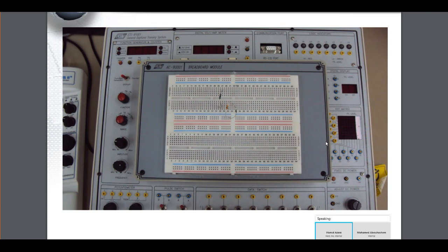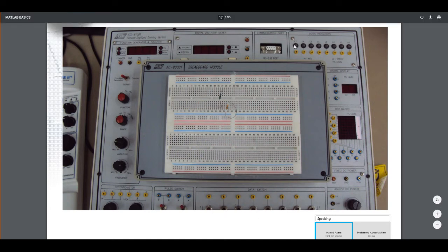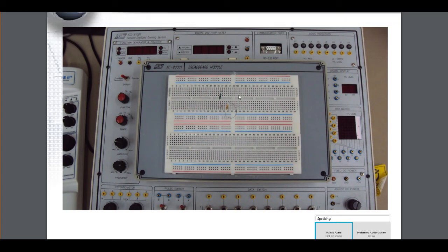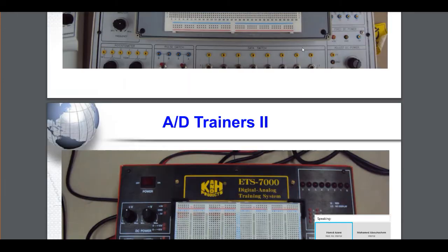Those are the equipment I was talking about at the beginning. We have different ones. For our first experiments, we'll be dealing with this part where we can represent the inputs using those switches. I don't know if you can see them. Those are switches, up and down, up and down. They are connected to ground the other side, so you can make 1 or 0, 1, 0, and so on. The output will be those LEDs here, depending on the number of outputs we need. On the breadboard, you can fix your IC, and you can connect the inputs to the terminals of this IC, and the terminals which represent the output for that gate to the LED here. We'll be working with that, inshallah, during the semester.